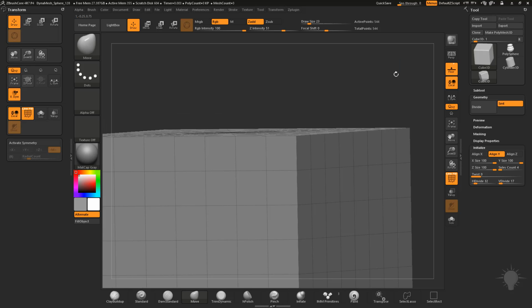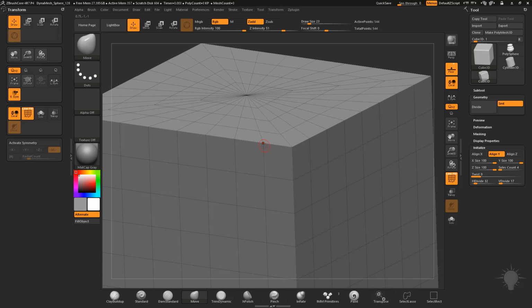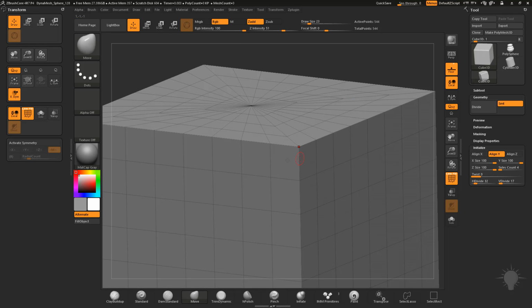So for each 3D object in your scene, you're going to have vertices. So if I kind of roll over these, you're going to see it's going to snap to those corners. Each one of those is called a vertex, and connecting two vertices is an edge. That's a different component. And then surrounding any poly face are edges, and those can be triangles or those could be n-gons depending on the program you're in. ZBrush doesn't usually work with n-gons, so it's usually a triangle or a quad, a four-sided face. So you've got a face, which is this broad surface here, surrounded by four edges, connected by four vertices.